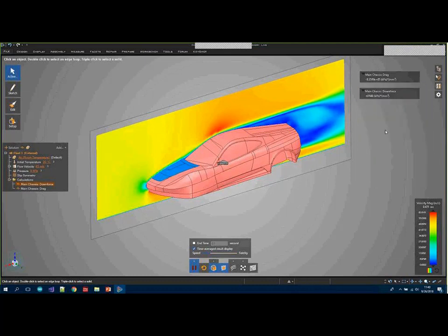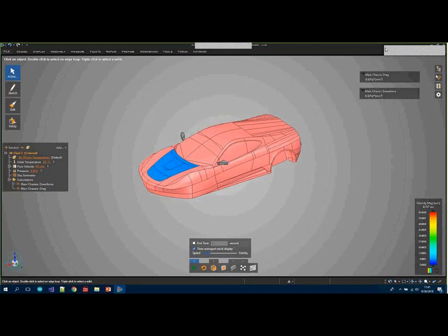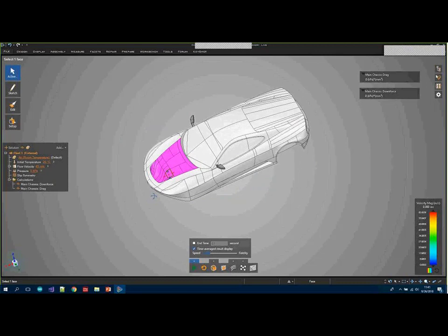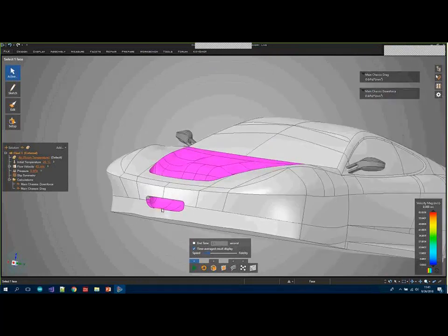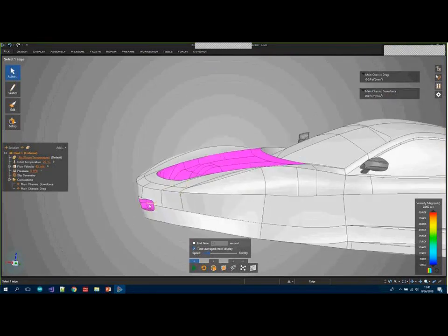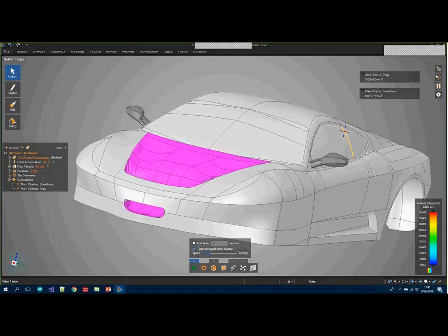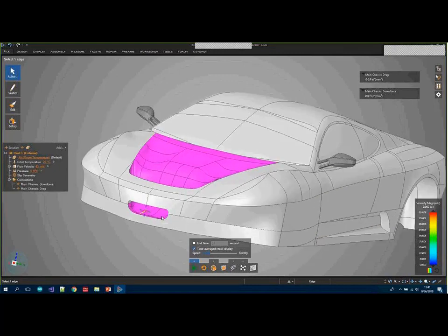Now, for the next example, or the updated model, here's what happened there. This was the classic design. The updated design has what's called an S-duct. Now, this S-duct is intended and designed to allow airflow to come in through the front here, where the grill area is. In these cars, it's a rear engine or mid-engine design, so radiators tend to be in the back. The airflow into the radiator would come in through, there's usually a duct over here for the intercoolers. And then there's some extra ducts around here to move the air around into the brakes and so on.